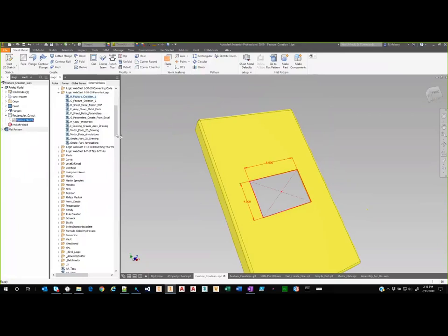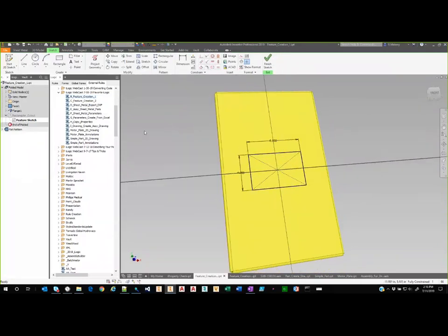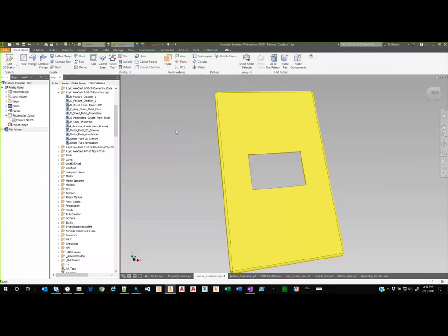If I take a look at the sketch in here, we'll notice that we are fully constrained, right? It is a 2-point center rectangle, and then I've got the width of that thing dimensioned, and I've got the overall height of that dimension. Again, that's being built on the fly. I can control what those values are, right? If I know what size that rectangle needs to be, I can size that however I want it. Okay? And this is a relatively simple sketch, and it's a relatively simple feature as well. It's just a sheet metal cut.